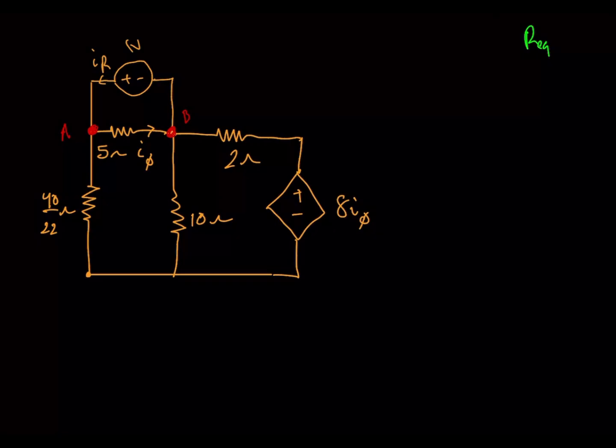So I'm going to use nodal analysis here, and I'm going to pick our reference node here and label this as this node. I'm doing this node because we have this test source here. So if we know that this is 0 volts, then we know that this node will be 1 volt because of this independent voltage source. I'm going to label this bottom node here V1.